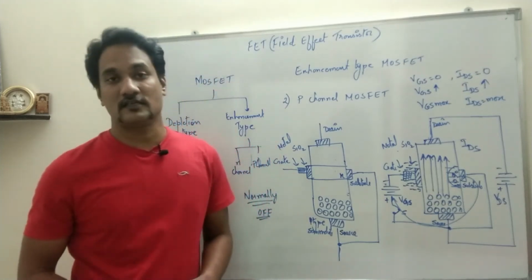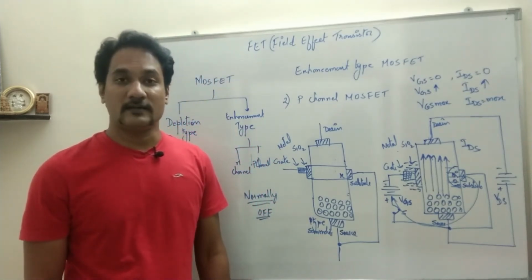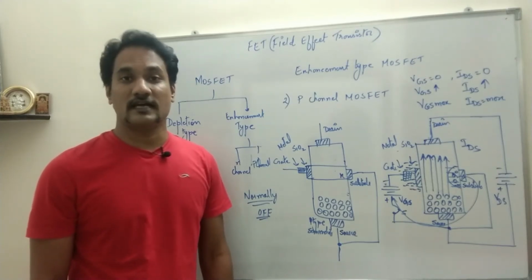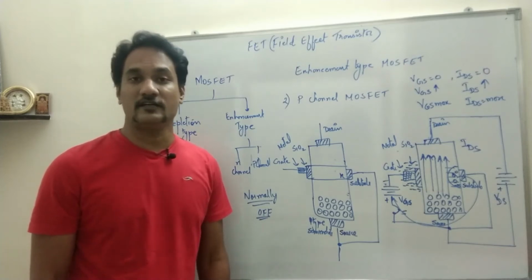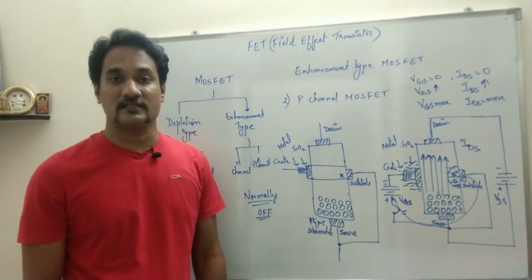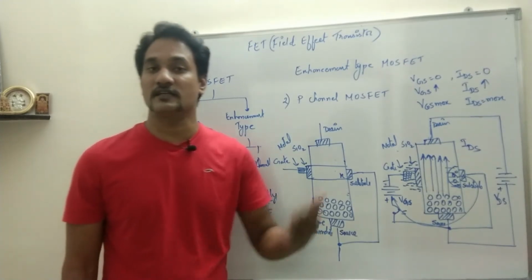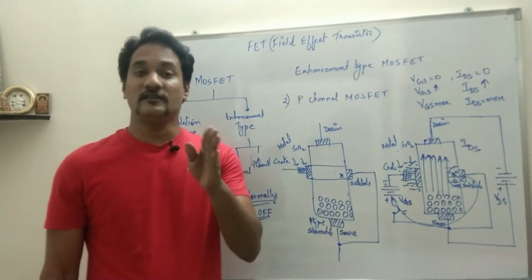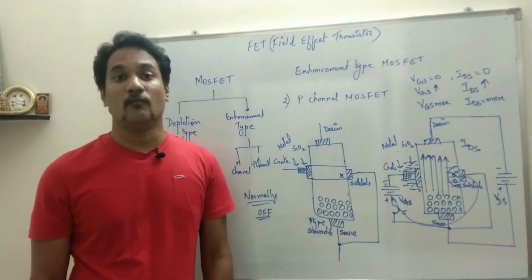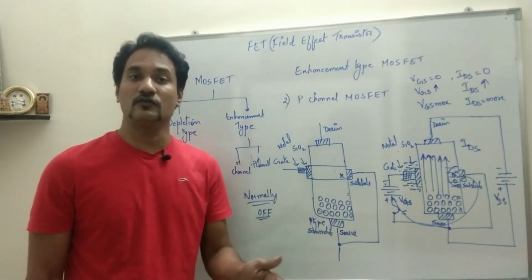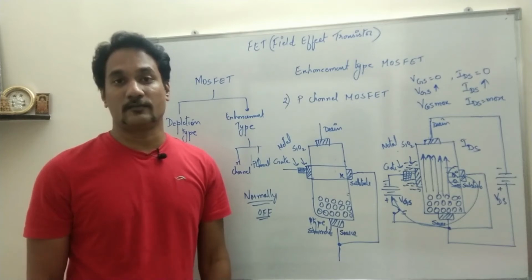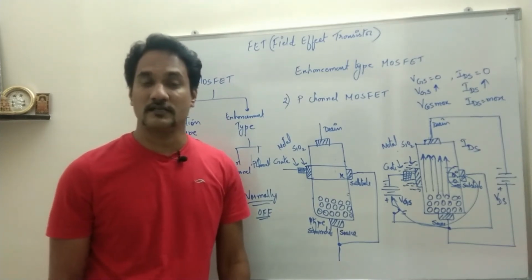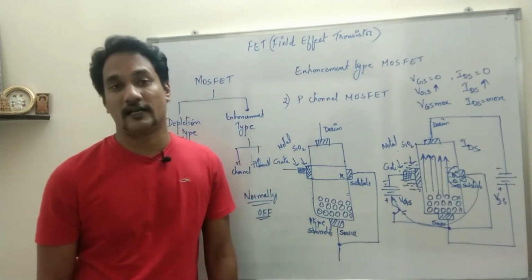Okay, so first thing what you have to do is you take a P type semiconductor. Okay, the terminals will be named as source and drain. Then on one side you form a PN junction. So to form a PN junction, we do pentavalent impurity so that we get N region, but that N region will be extended almost towards the MOS. So on the other side, what you have to do is, over the semiconductor layer you have to deposit oxide, which acts as an insulator, over which there will be a metal deposition, and the terminal which will be taken out will be called the gate.